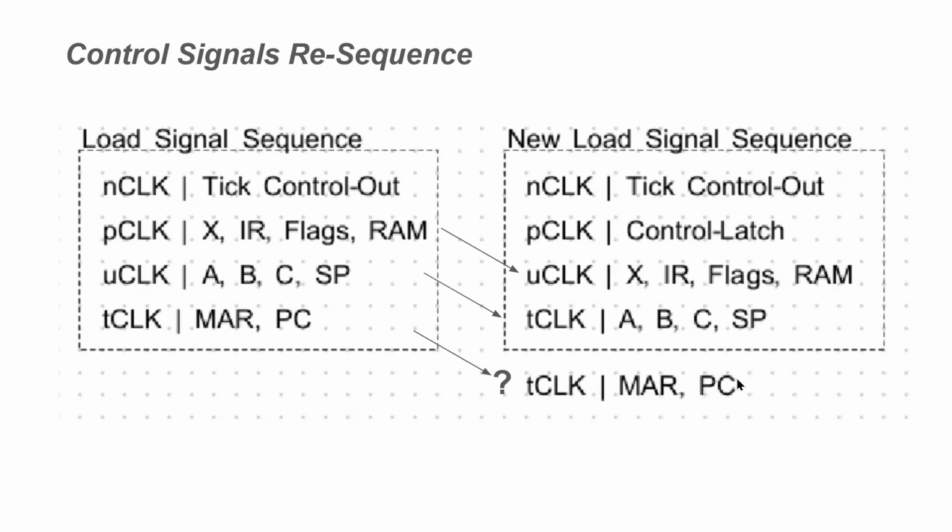Remember, we have 16 microcode ticks, since the tick counter is 16 bits. We had just enough to do the call statement by adjusting the microcode. So that was our first part of the changes. We shifted everything down in our clock phases. We reused the P clock for our control latch, and we had to update our microcode into two microcode steps if they were one.